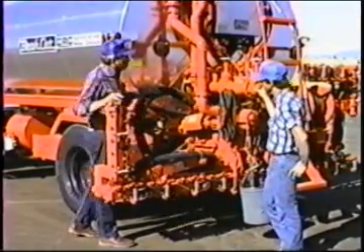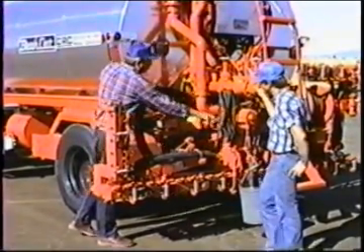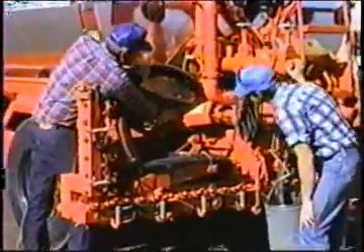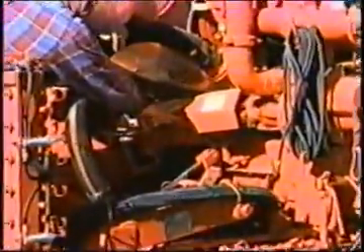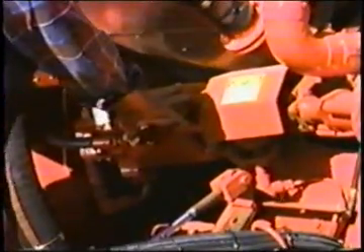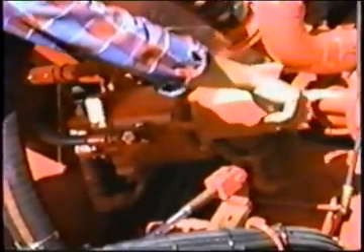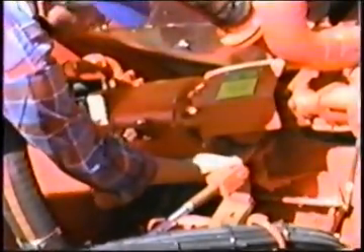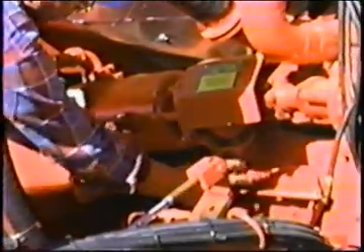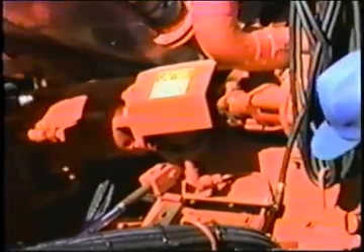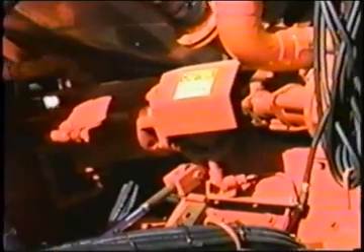We have control of the pump with the hydraulic motor. Now this is the hydraulic motor, this is the work end of the hydrostatic transmission. It turns the asphalt pump. Here on the shaft is a gear and a gear tooth sensor. Those two things tell us the speed of the pump.